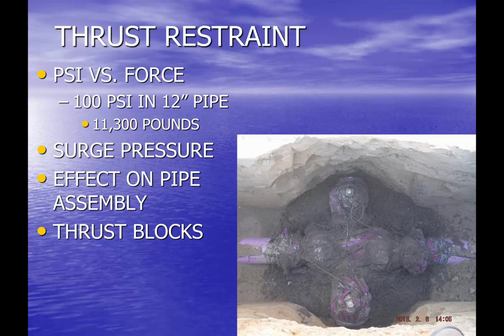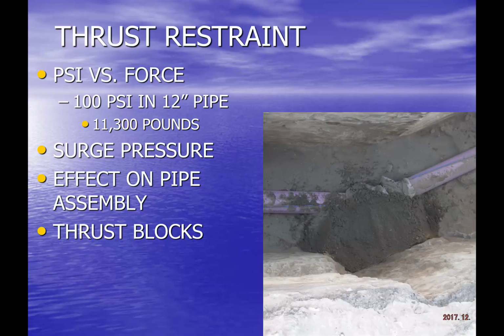This picture, again from the Recycled Water Project, shows essentially a cross, with valves going a couple of different directions, so they've got what really amounts to thrust blocks on all four corners. This one is a slider bend, looks like a 22.5 degree fitting maybe, but with a thrust block, and you can see that it's poured against the undisturbed portion of the trench.